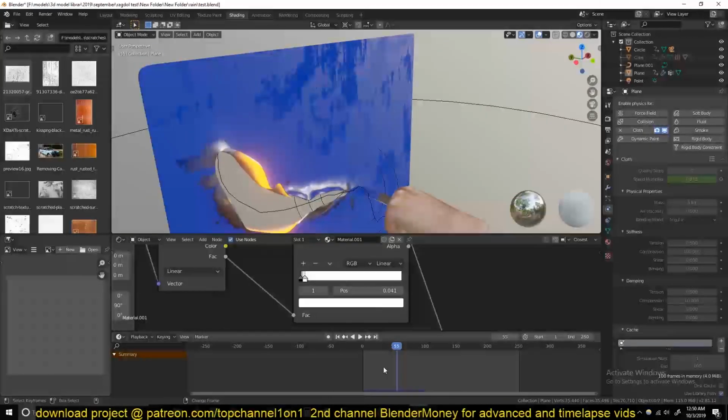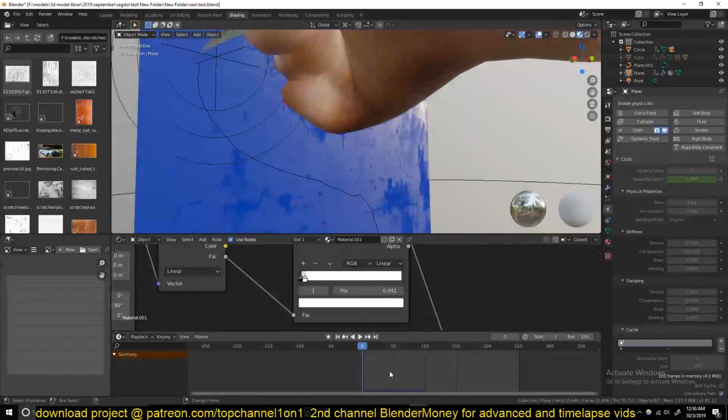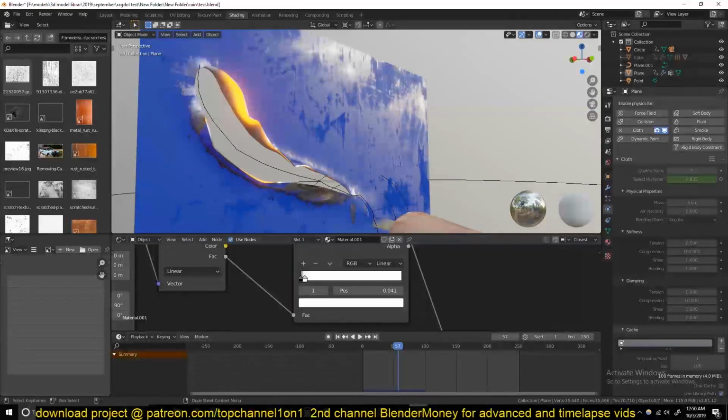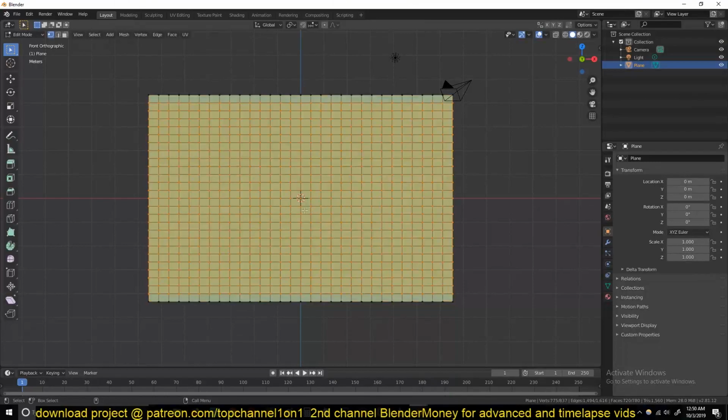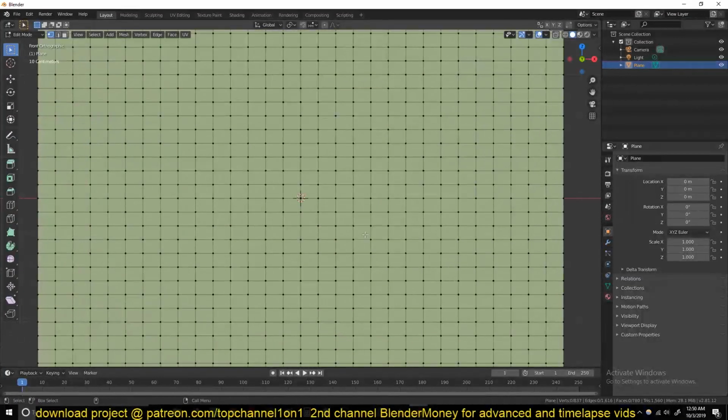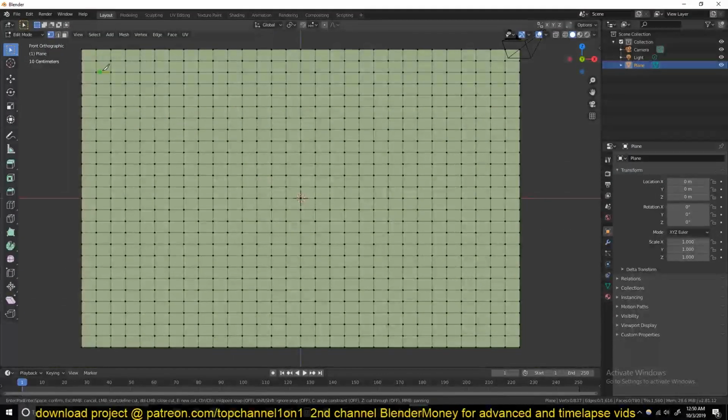Now, to set up this claw or whatever it is, this tearing, we need to make this cut here first. And the way you do that, I just go to edit mode and I use the knife tool. I don't know if it's here. Let me see. Okay, it's here, but the shortcut is K. You just hit K, and then you can draw. Just drag and draw the shape you want. So let me zoom in a bit. The more subdivisions you have in your mesh, the smoother your cut will be.